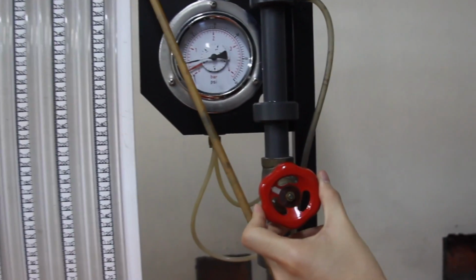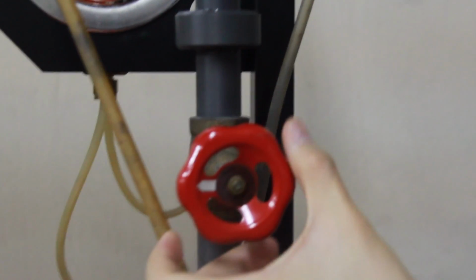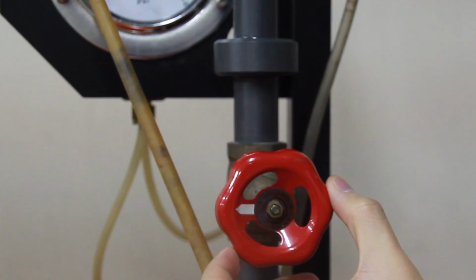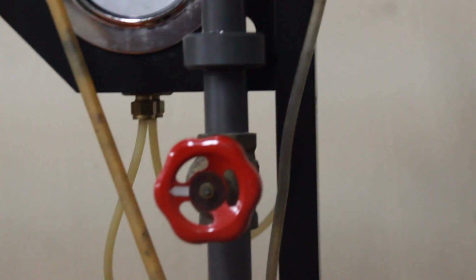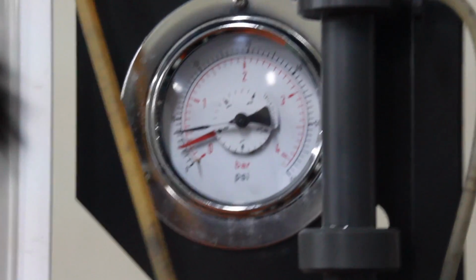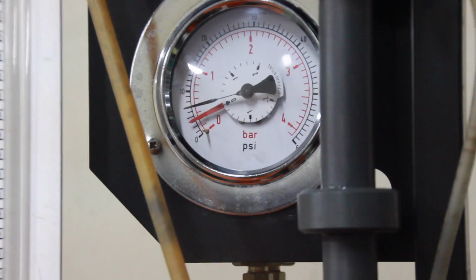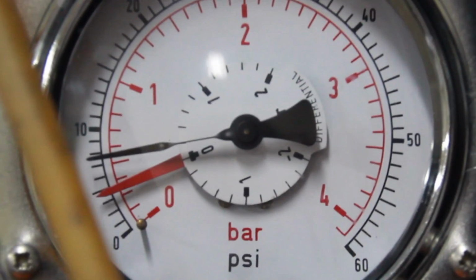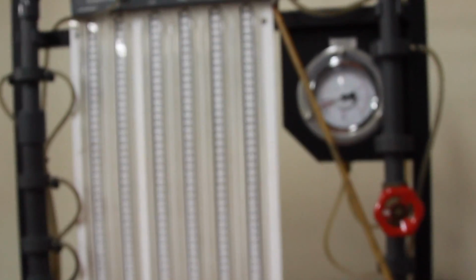The third trial is opening the gate valve approximately 75% of one turn. Repeat the process done in the first and second trial, by measuring the pressure drop across the valve using the pressure gauge, adjusting the flow rate by use of the test rig flow control valve, and determining the flow rate by timed collection for the third time.